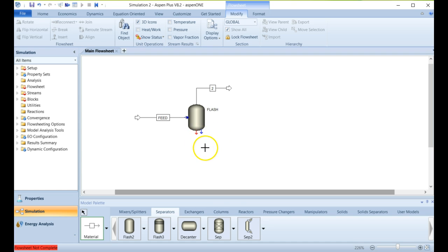These are not required, and one of the most common mistakes I see in Aspen is students on the bottom click the water decant stream to connect to it as opposed to the actual liquid required stream. So don't do that. No clicky on the water decant stream. Do not do that. So if you can avoid that, that would be very good.